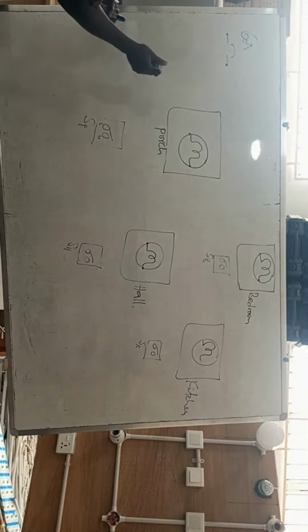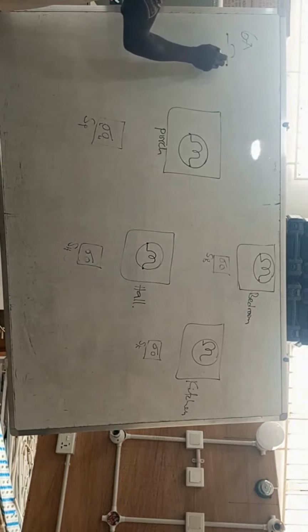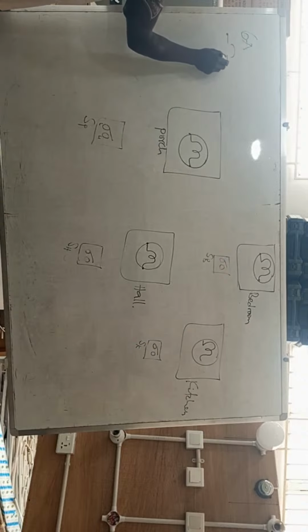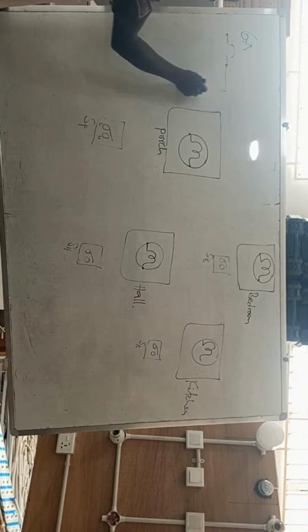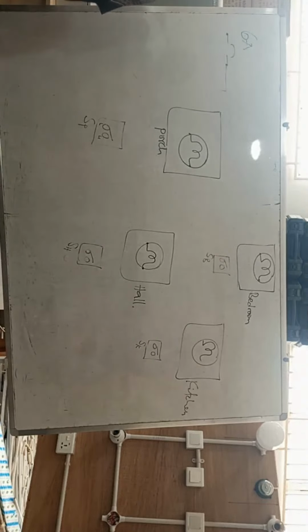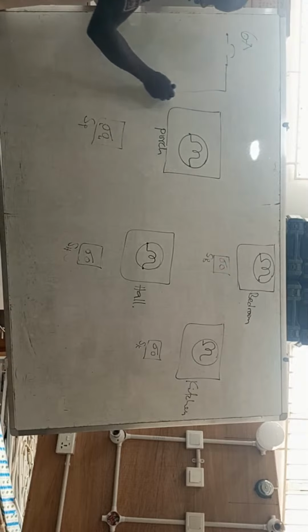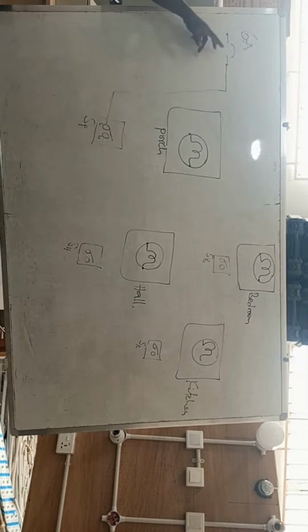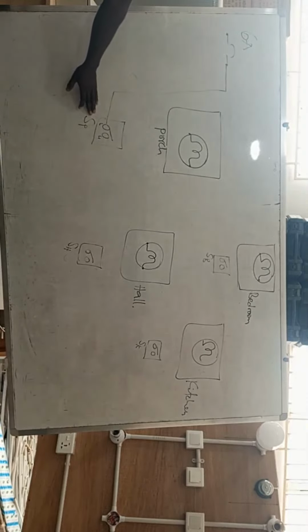We will pick a feed, or we'll pick live from the output side of the breaker, and then it will first come to the L terminal of one of the switches. So the closest switch to our breaker, which is obviously in the consumer unit, is the switch that is controlling the light in the porch.